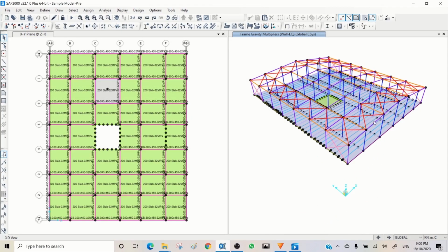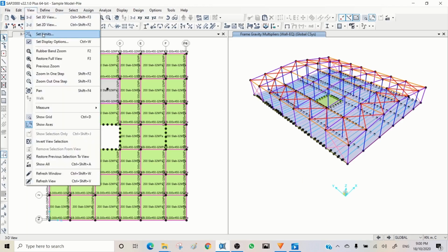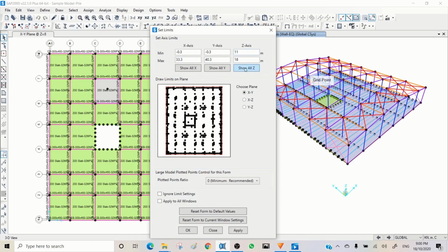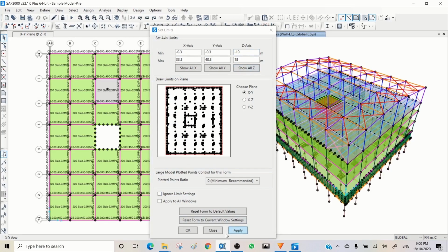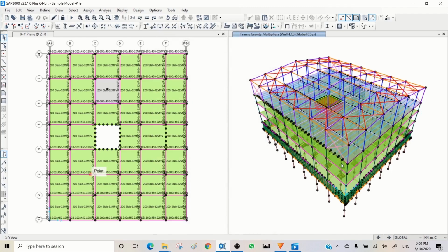Roof wind load, internal wind pressure, is not just windward and leeward. So you really need to check your local standard and see what are the requirements, and according to that you can complete your wind loading and also load combinations, and then complete your analysis. We will go through the details in our workshops, but I will leave it as it is by now, just to keep things simple. And I just tidy up a little bit this model, and we will continue for completion of our load patterns for earthquake and wind load.